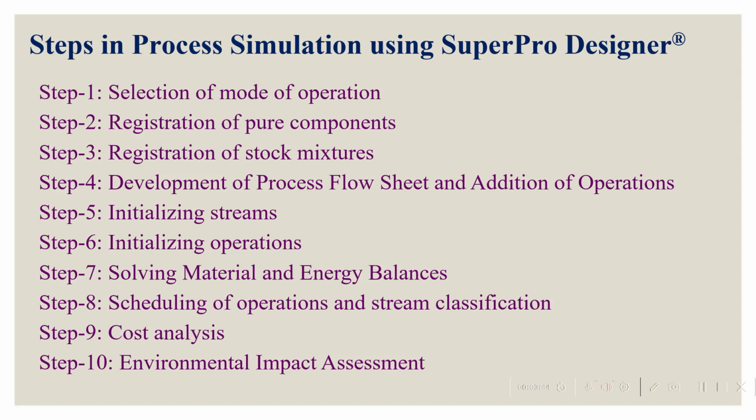For example, if you are using a batch reactor, we need to charge the reactants, heat the reactants, and allow the reactant mixture to undergo the reaction. Then once the reaction is completed, maybe we will transfer it out. So it is not limited to 3 to 4 steps. Depending upon the problem statement, we might have multiple steps in each unit procedure. Once you initialize all the procedures and streams, then we need to perform the material and energy balances.